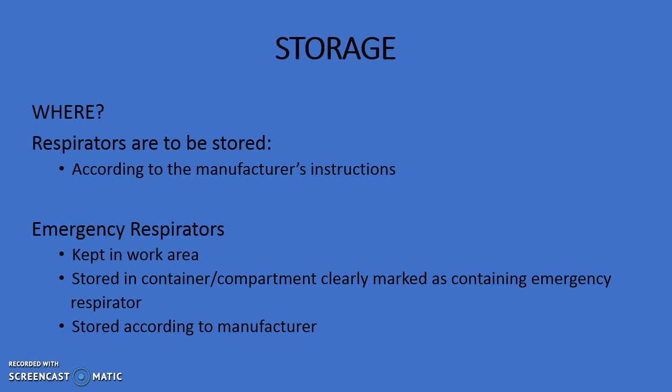Emergency respirators must be kept accessible to the work area, but not in an area where it might become involved in an emergency and become contaminated or inaccessible. Store them in a compartment or cover that is clearly identified as containing emergency equipment and store according to the manufacturer's instructions.